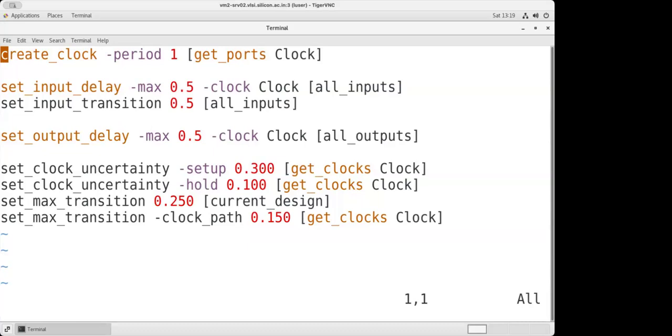That means you will get those files either from the foundry or from the EDA vendor. So if we are talking about Cadence, and you are using the Cadence tool, you can get them from Cadence, or from Synopsys, or maybe from Siemens. It depends on which tool you are going to use. Those files are going to be read by the tool, and that's the reason I'm saying you can get those files from the foundry and also from the EDA vendors. But EDA vendors are going to provide you those files only if they have a relationship with that particular foundry.